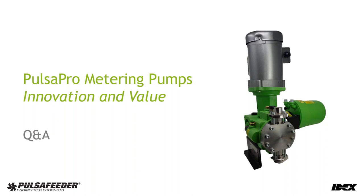So as that hydraulic performance valve injects hydraulic fluid behind the diaphragm, the makeup valve will open and allow fresh hydraulic fluid to come in from that pump head reservoir and fill that void behind the diaphragm. So they really work in conjunction with one another. Every time that hydraulic performance valve is activated, the hydraulic makeup valve also is working to allow fluid to come in if it's needed behind that diaphragm.